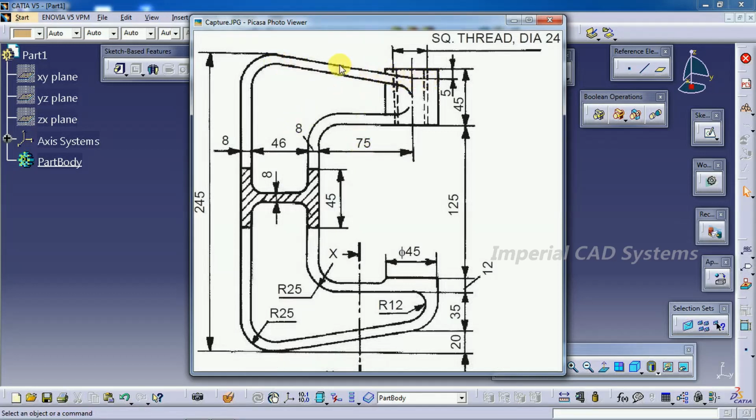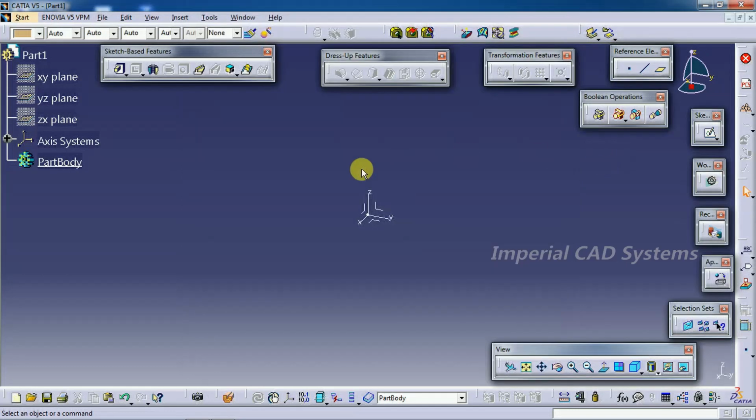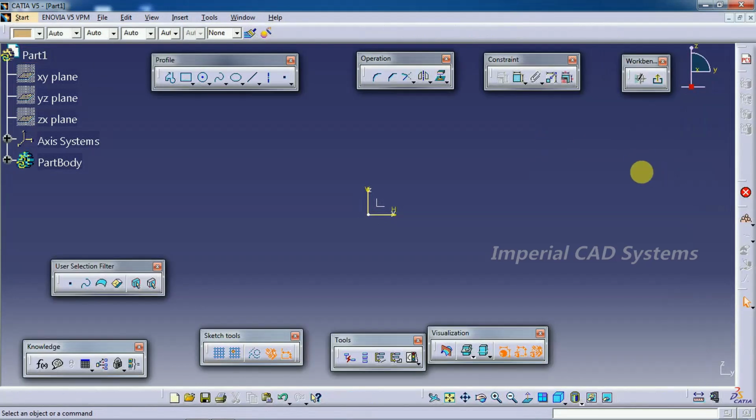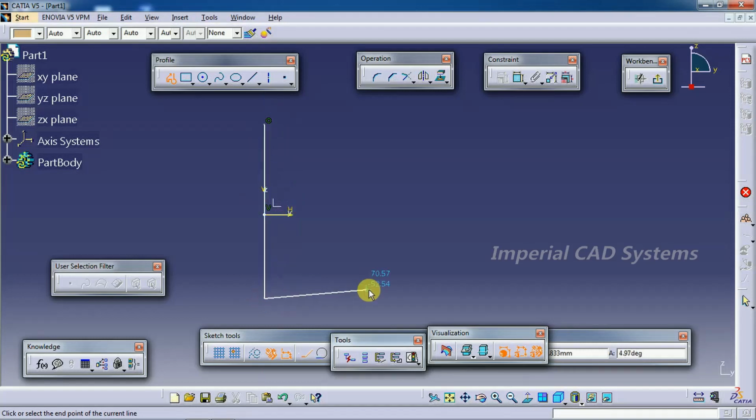First, take this profile, the outer profile, in the Sketcher and extrude. See, here a revolved section is shown, which is an I section. So first I go to Sketcher. I select the plane and go to sketch. Create that profile. Like this it is. Parallel.